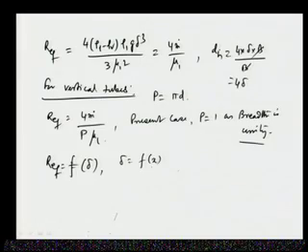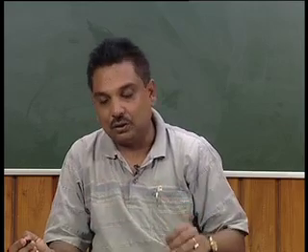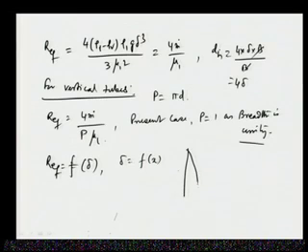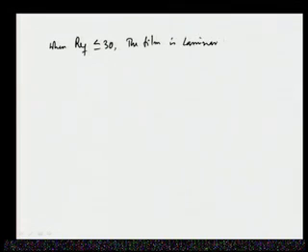So, what is happening as we are moving along, in case of condensation over a vertical plate. So, this is the x direction. As we move down, the Reynolds number goes on increasing, and then what is being said here is that when Re_F is less than or equal to 30, the film is laminar with no ripples or waves.